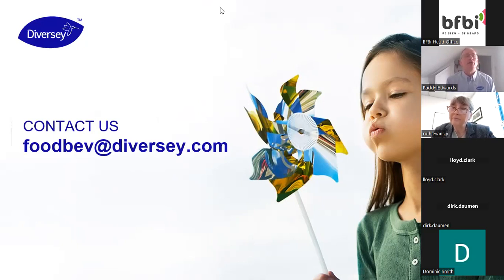They get paid on their acceptance criteria, and therefore they ensure that the CIP set is set up with parameters that will ensure that they pass the acceptance criteria. So it's effective, but no way are they normally efficient. And therefore, by going in and optimizing the CIP set, you can save significant quantities of water and energy and time.